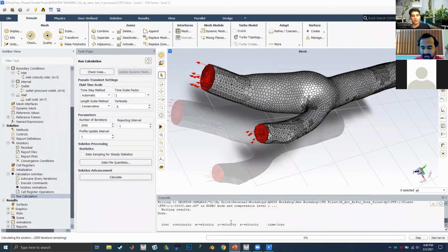So more or less, when calculating solutions, what would be the expected timeline for it to solve? Like how complex can it be? Oh, you can get really complex. I've had simulations that go longer than a day, or even days before. That was when I was running really large models that were 1 million plus elements with nothing else running on my computer. But I've also had the exact opposite, where I've had very simplified cases that run in less than a couple seconds. Like it'll take longer to set up the model than to solve it. Right. So it really depends on what your model is, what the details are, your boundary conditions, steady state, transient, and so on and so forth.